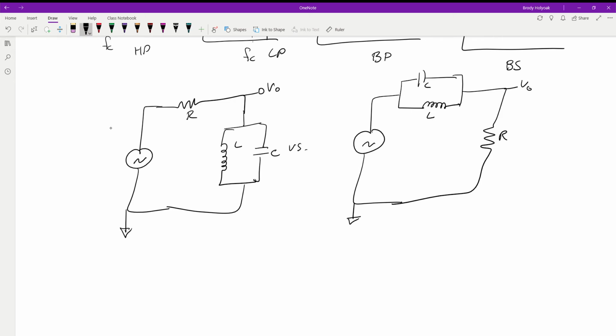And the values that we have, so we have a 56 kilo ohm resistor. We have an inductor at 2.4 millihenries and 132 ohms of winding resistance. And our capacitor is 330 picofarads. So this is the example we're going to go through, and then later we'll fill out the last little bits of information like in our homework based on the same problem. That way we can reuse the numbers and don't have to create quite as much. So that is the circuit we're going to be working on.